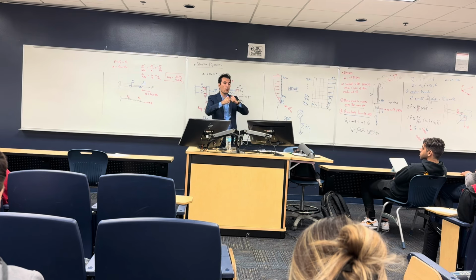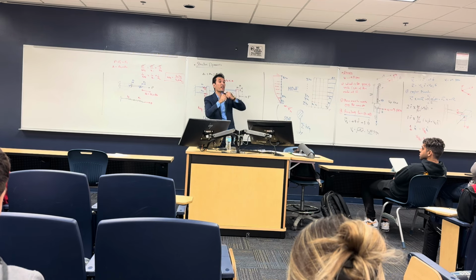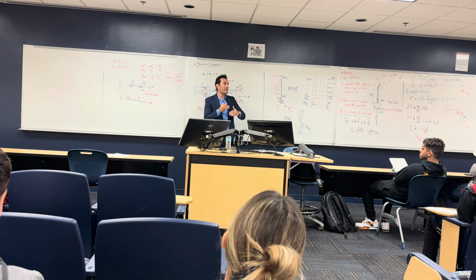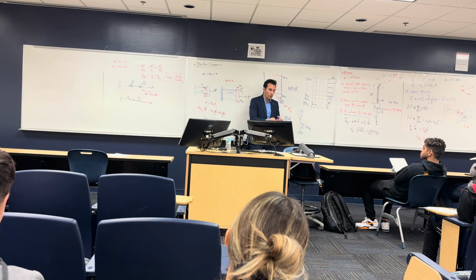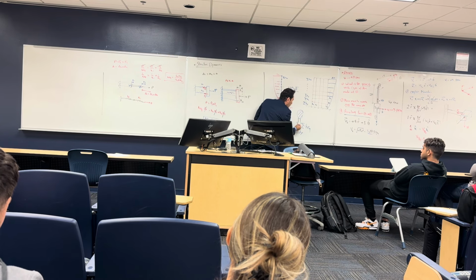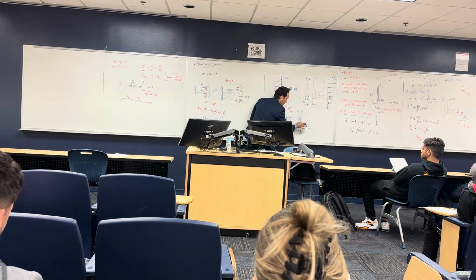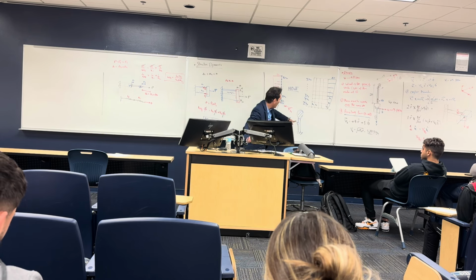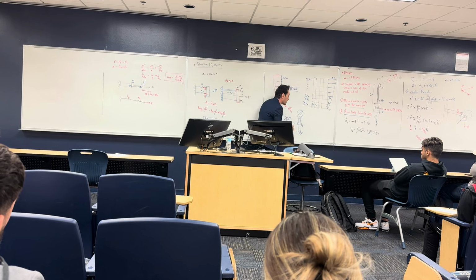What is damping? When you have a joint, like a column and a beam, opening and closing, there are cracks. Opening and closing of the cracks adds damping, making the force die out. So that's why we add this component. I'm not going to talk more about it. Sometimes people solve systems and say, I'm going to neglect the damping. So the spring line that I have here, this we call stiffness, K, and this we call C, damping.